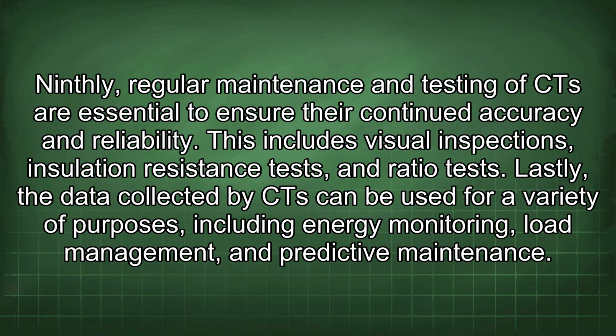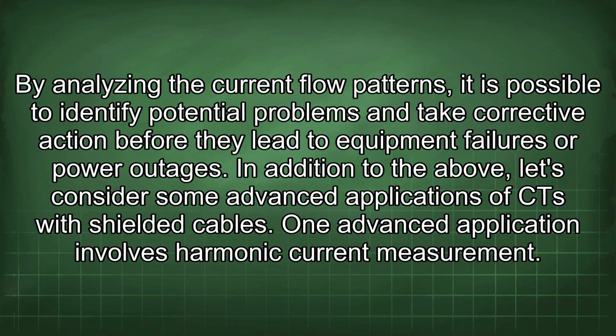Ninthly, regular maintenance and testing of CT are essential to ensure their continued accuracy and reliability. This includes visual inspections, insulation resistance tests, and ratio tests. Lastly, the data collected by CT can be used for a variety of purposes, including energy monitoring, load management, and predictive maintenance. By analyzing the current flow patterns, it is possible to identify potential problems and take corrective action before they lead to equipment failures or power outages.